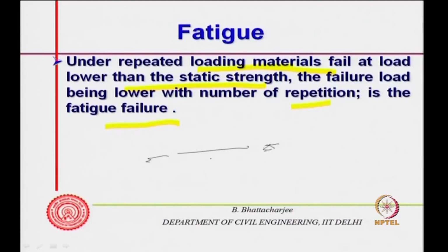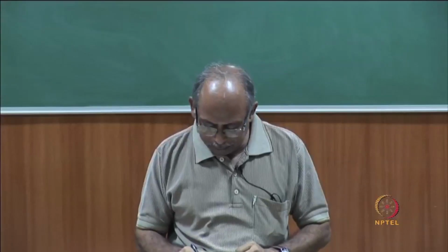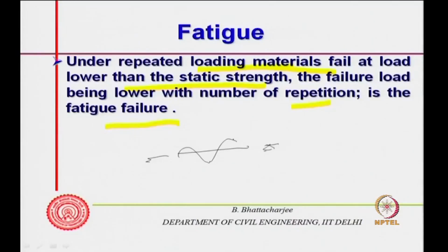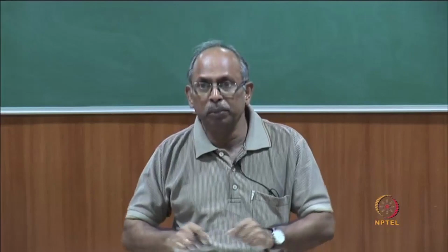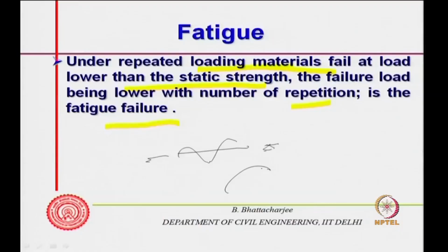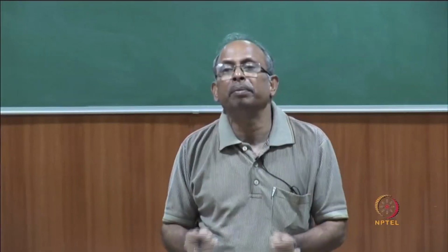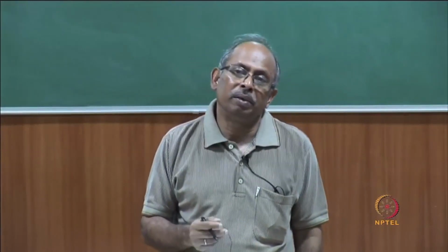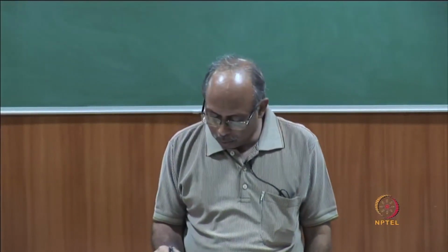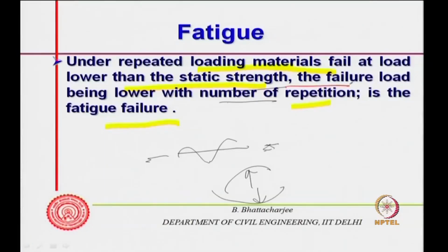But if I try to bend it in this manner, that reverses the stress. There is a reversal of stresses. So, first you bend it in this manner, then bend in the reverse direction. You go on doing this, and after some time it will break. So, with repeated loading it fails at a much lower load, and that is basically a fatigue failure.